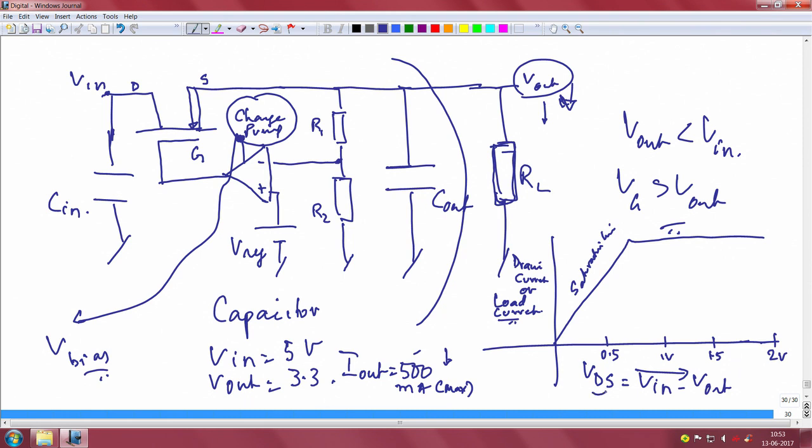That is the voltage that has to drop across this series element. Here you can see it is quite simple: if V in is 5 V and V out is 3.3 V, then VDS is nothing but V in minus V out, which is 1.7 V. So, 1.7 comes somewhere here, let us say, alright. And now let us take drain currents, let us say 0.5 amps, which is the maximum load current, and that point comes here. So, let me draw a line like this; 1.7 comes here. I am sure you will all agree to this point. Okay.